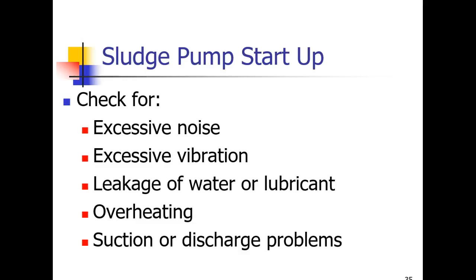Sludge pump startups. You always want to check, on any pump startup, for excessive noise, excessive vibration, leakage of water or lubricants, overheating, suction or discharge problems. One of the things that as a seasoned operator becomes more and more experienced, it's kind of like a car mechanic. A car mechanic can listen to a motor and hear things that a normal person can't hear because they work around those every day.